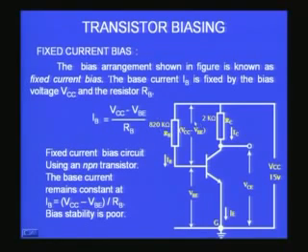For considering this type of biasing circuit, all the knowledge that you have to have is just simple Ohm's law and some basic circuit ideas like the KVL and the KCL. Now can we calculate what will be the base current for the given case here with VCC 15 volts and the RB, the base resistance, is 820 kilo ohm. What is the base current?